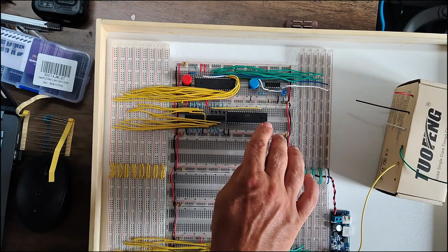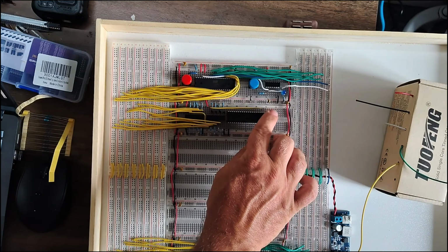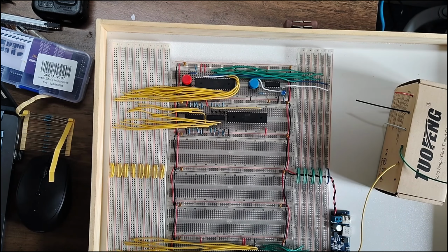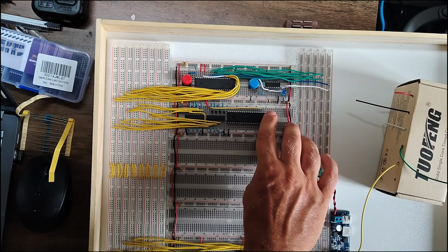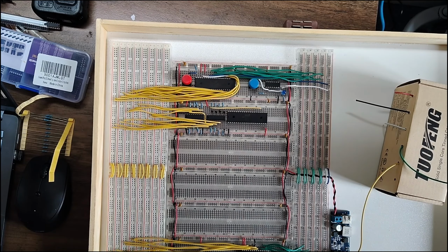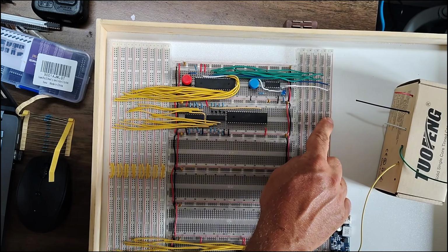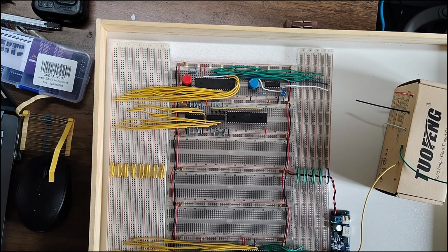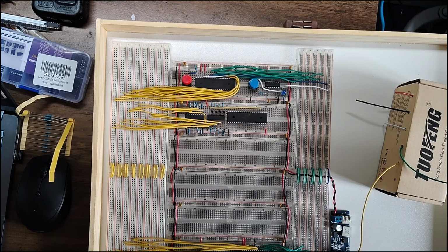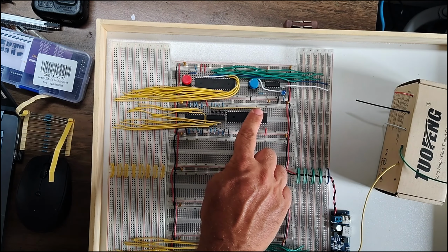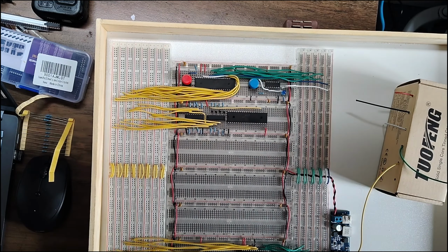So over at this end, the first pin over here is an interrupt request pin. We're not bothered about that, so we don't need to do anything with it. The second pin in is a read-write pin, and that needs to be connected across to the read-write pin from the processor, so that the processor knows whether it's reading or writing to the outputs or inputs. And then also over here there's a clock pin, which we're not using at the moment, but it's useful to connect it up, so we'll connect it up to the clock of the processor as well. So let's get those done.